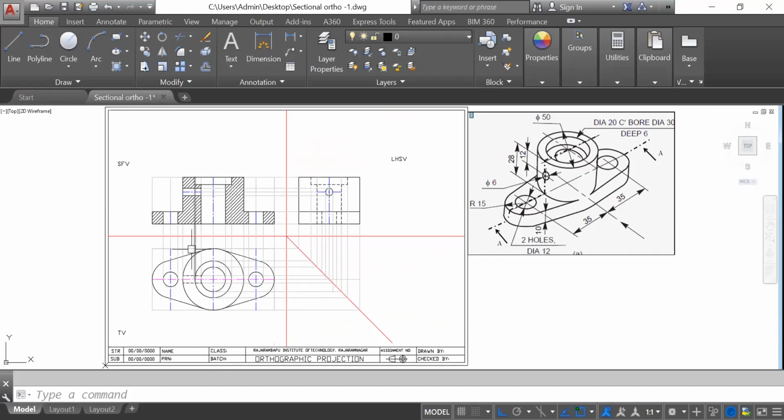So without a section, this part would be hidden. But when we take a section, then that would be visible, and that's why it is required to show it by section lines. So slowly you can imagine how the sections work. The basic funda is that you just consider the whole object is being painted. Wherever holes are there, inside the hole I can also paint with the brush.